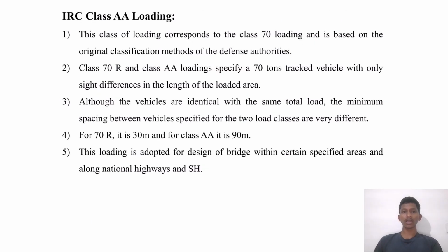Further, talking about the IRC class AA loading, this class basically corresponds to IRC class 70 loading. By class 70, they mean that 70 tons of load can be considered for the design, and a 30 meters to 90 meters span can be considered.